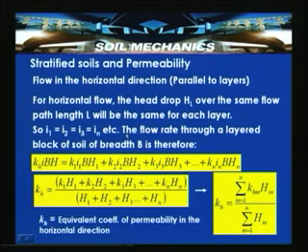So, if the head loss is the same, then the hydraulic gradient in the first layer, the second layer, and the last layer, that is the nth layer, can be the same. So, a condition is that I1 is equal to I2 is equal to I3 is equal to I4 is equal to In.